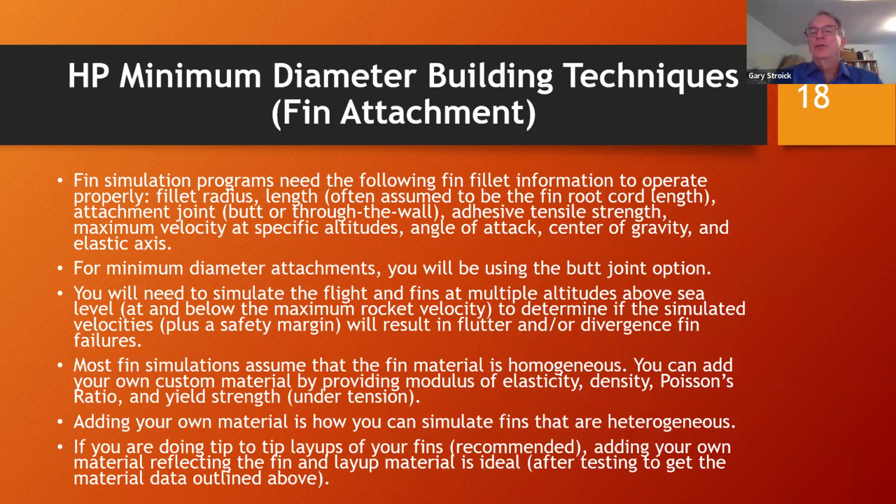You'll also need to know some other information, like where the center of gravity of the fin is, and something called the elastic axis, which I can help you with. Basically it's a line along the fin where, if you apply force, the fin only bends. It doesn't create any torsional or angling forces on the fin at all. So that's what an elastic axis is, if you see the term when you're looking at these different potential applications.